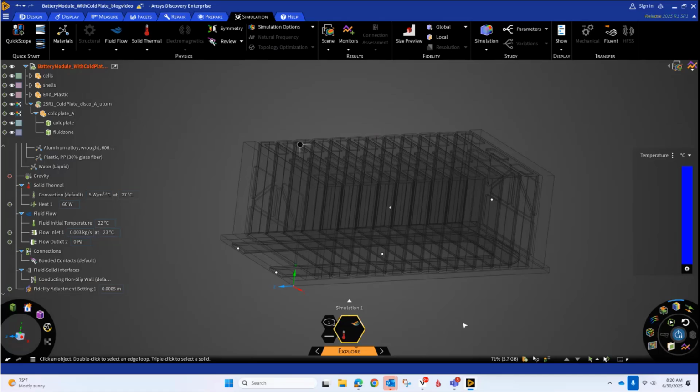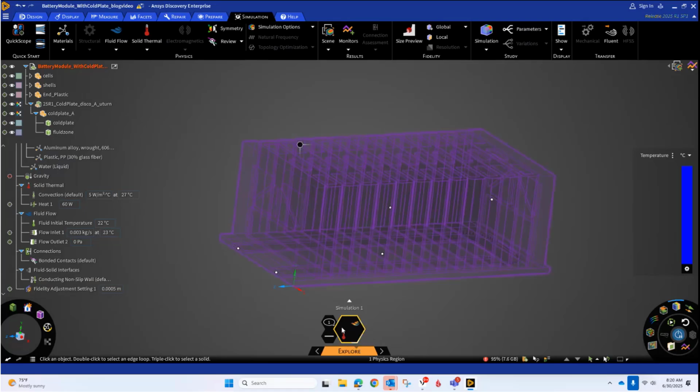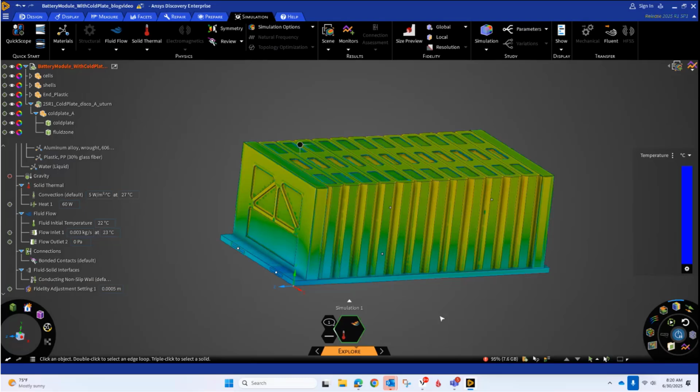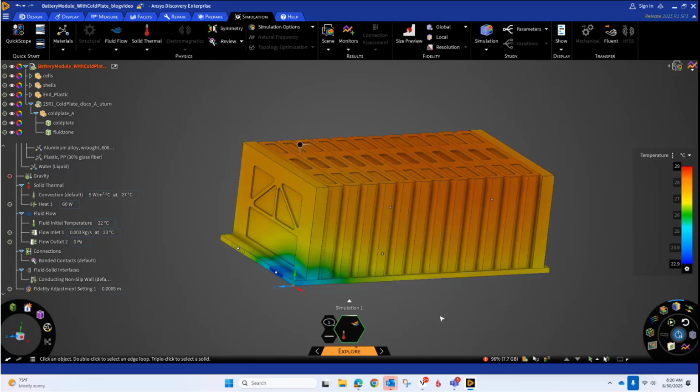You can see the progress going around, the little white highlight going around the yellow as it's meshing and doing the actual iterations. It's getting close to being done. As everything turned green, it still says it's solving. You already see a contour of temperatures on the external surfaces. The legend for the temperature isn't changing much in terms of maximum temperature, and our simulation says it's complete.